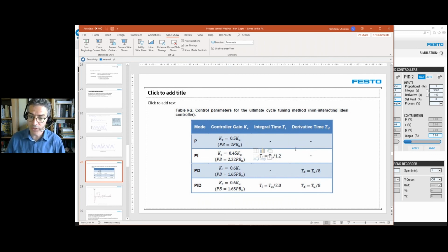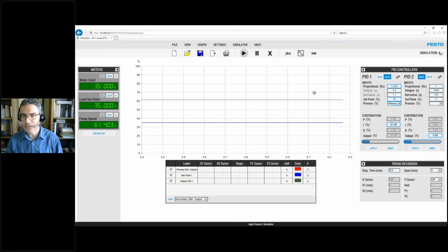So, for example, if we were to do it, I'm concluding with that really quickly. If we were to do it with this, again, the same setup, the same process that we just did for our Ziegler-Nichols, I will quickly tell you that we found that the proportional gain that will yield steady oscillation is 15.6.